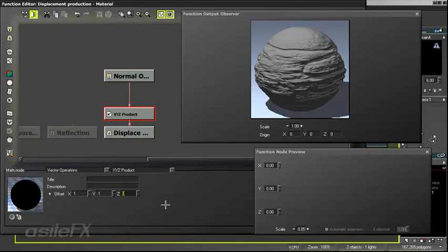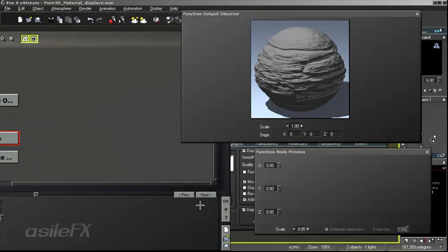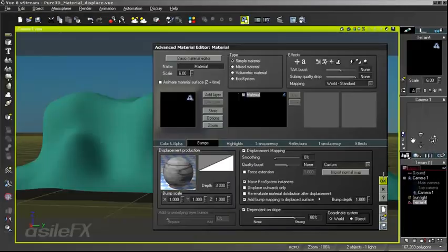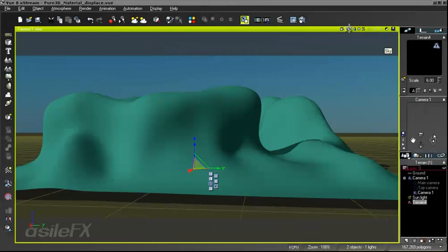By setting it to 0, it is not using any of the Z information. I like to just modify that 0 to around 0.1 or so, sometimes a little higher, basically just reducing the displacement on that direction rather than removing it completely, because sometimes it'll cause tears or a poor displacement.